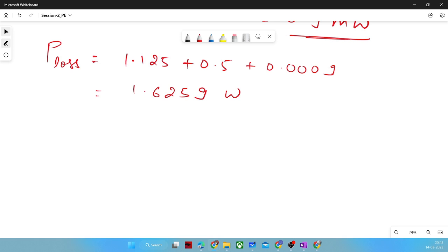What is written here is that the base driver source should have the sinking capability so that negative base current can flow. It should have that much capability so that it can remove those charges which get stored during the off period. That is what this first statement means. It means it can withstand that much negative voltage, if you apply negative voltage at the base.